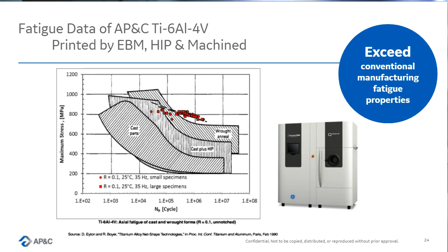And one of the things that is known, and has been shown, is that even if you have argon in your powder and it ends up in your part, you're going to see that the pore is closed, but it's still there. The argon is not going to diffuse through the matrix, and it's not going to react with the matrix. And papers have shown that if you apply heat or stress, it's going to grow back to the original size, and porosities are known to be fracture-initiating sites.